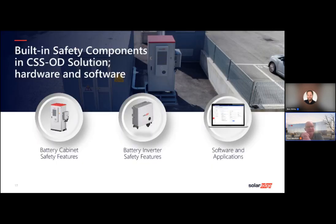Now, if we look at the safety components, like I say, it has always been a great watchword for SolarEdge. Yes, it should be for everybody, but I think we've made it key to everything we've brought to the industry, particularly on the solar side with our SafeDC, bringing the voltage down to 1 volt per optimizer, and also our Sense Connect, monitoring the temperature of all the connectors connected to our S range of optimizers. That sort of philosophy is now being utilized for the battery storage systems that we have.